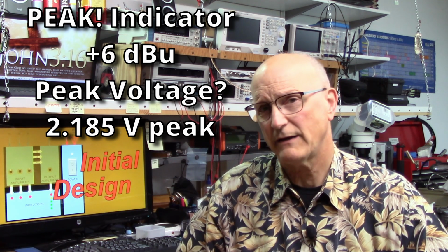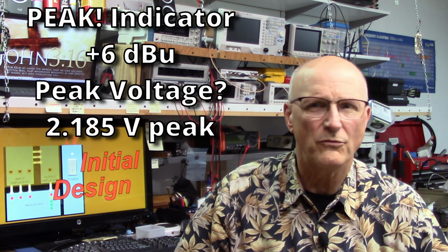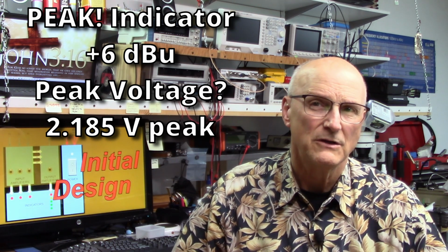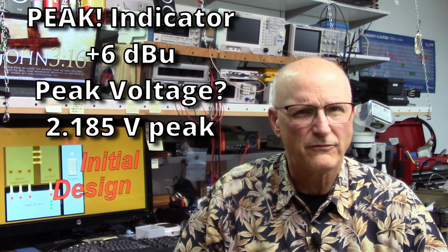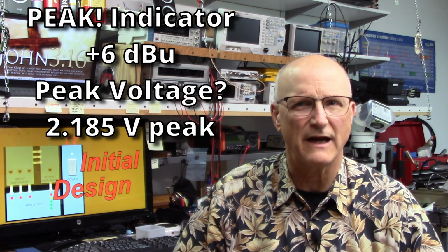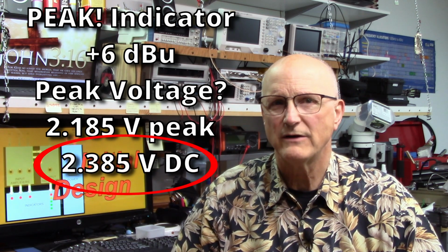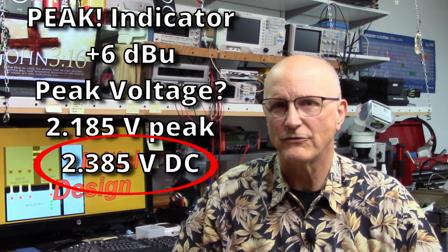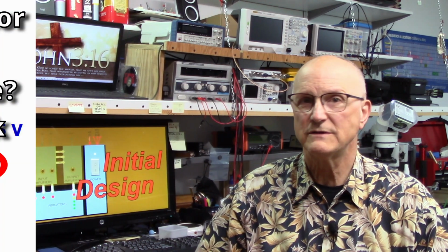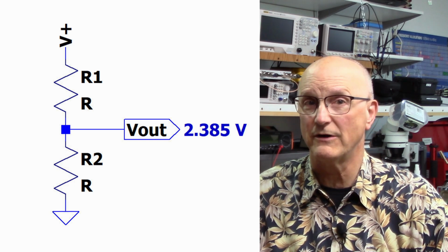But this peak detector gives us 2.2 volts out with a 2 volt peak signal in. So our compare voltage needs to be 0.2 volts higher than the actual desired threshold voltage. This gives us 2.385 volts. We will use a voltage divider to provide this reference voltage to the comparator.